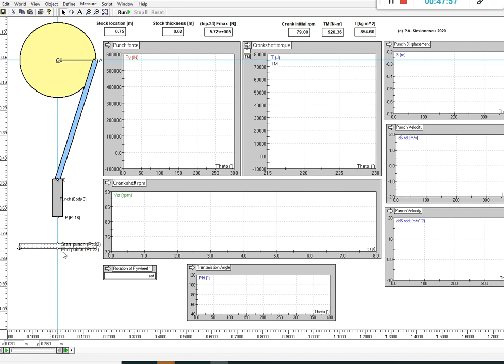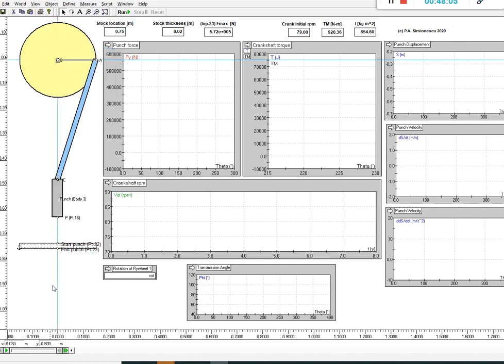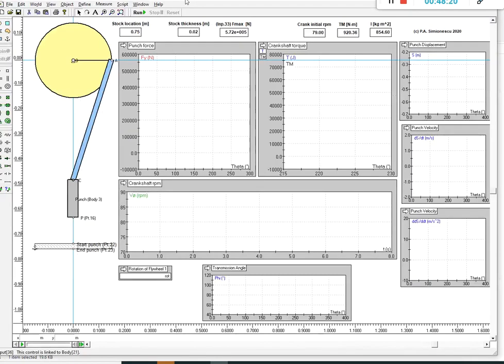the workpiece. By the way, these bodies neither collide, so Edit, Select All, Objects Do Not Collide. They don't collide. It's not like Working Model is so smart and knows how the steel material behaves when a punch travels and gets forced through it. Okay, hope that's clear.